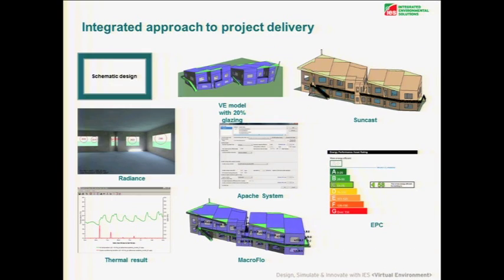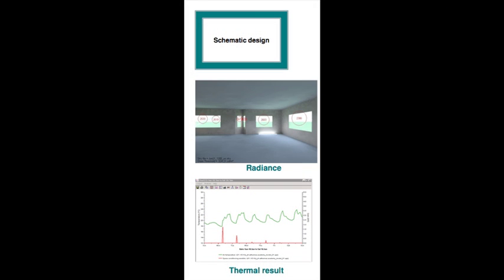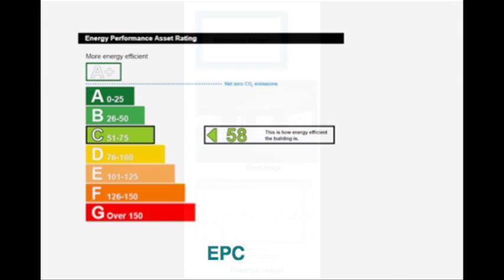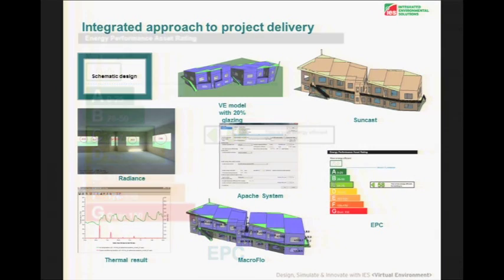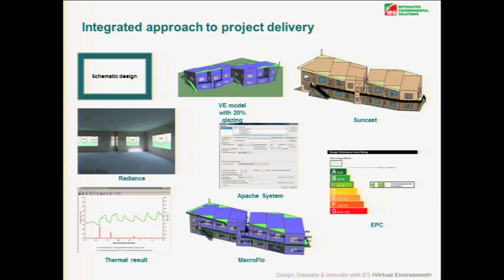Into schematic design, we might have a preferred option. We can start to look at compliance, so UK compliance with Part L, EPCs, again BREEAM, or if it was elsewhere, we could be starting to get some early feedback on LEED performance as well from the earlier stages. Again, refining the data, so integrated feedback on the glazing configuration, for example. That will give us feedback on energy, daylighting, any glare issues that we might get. We can look at all of those things within the software.